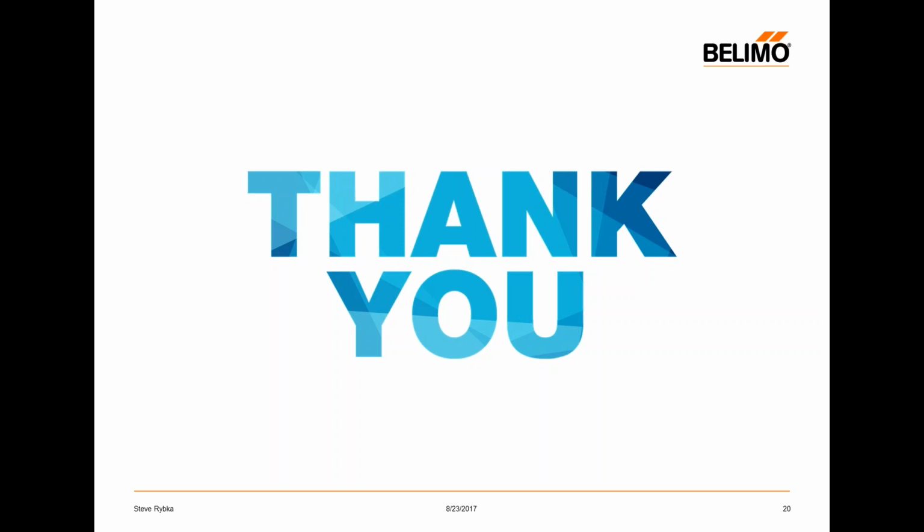That's a great question. One of the things I did not go into during the presentation is the energy valve has the capability to data log. So it data logs a bunch of information over two different specific data sets, a short-term data set and a long-term data set. So what we could do is essentially size the valve as accurately as possible, put it on the coil or the air handler, and monitor it and just see how it performs. Then the data can be extrapolated from the valve, and we have a tool that has been built called the Energy Valve Data Analysis Tool. That information can be pushed up into the data analysis tool.